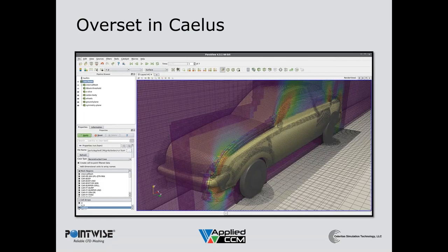So here I'm just using ParaView to highlight this. In the filter pipeline in the panel on the left-hand side, maybe a little hard to see because the text is small, there's a filter called iBlank-threshold. It's a threshold filter that uses the iBlank field to disable the display of the hole cells, and the hole cells have an iBlank of 0. All the non-zero values are active cells, and that's what I'm showing here.